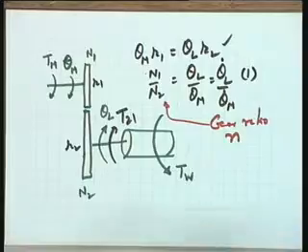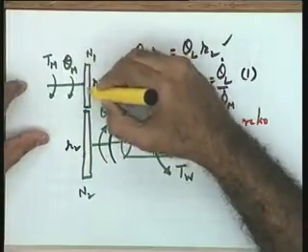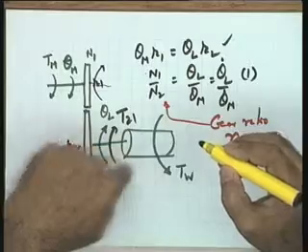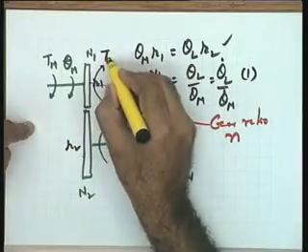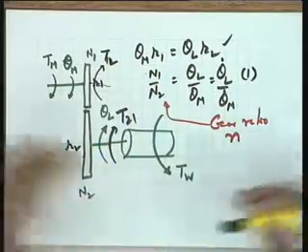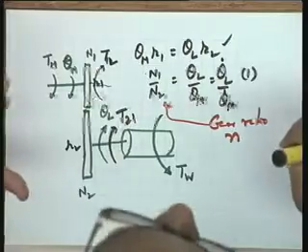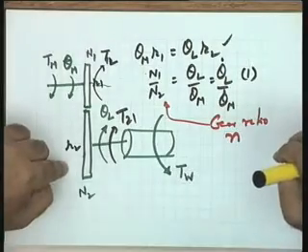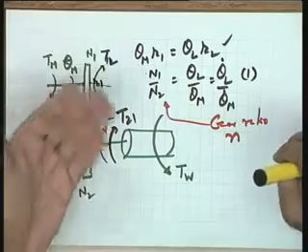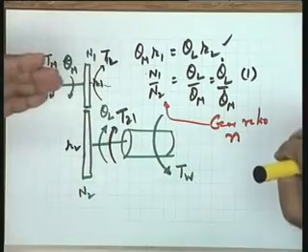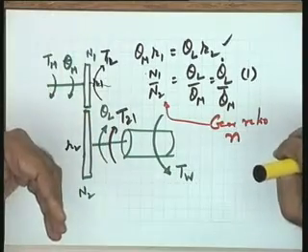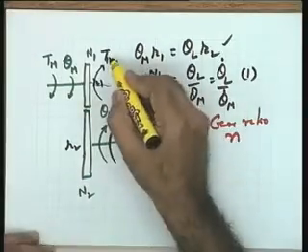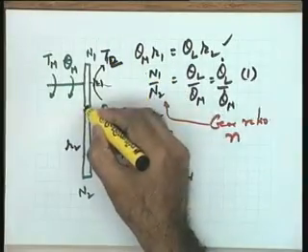And let me say that the total load provided on the motor shaft by the gear and by this particular load is T12. So I put it again: T12 is the loading of the motor shaft due to the load and the secondary gear, or gear 2, and T21 is the drive torque transmitted to the load shaft by the motor shaft.